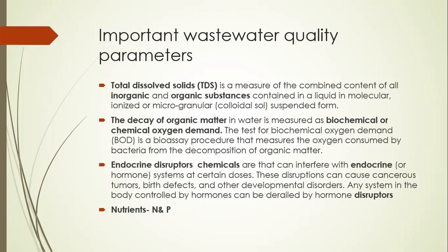How we can measure the presence of organic substances in wastewater is through the biochemical oxygen demand parameter, or BOD, and it measures the strength of any wastewater. So if you want to know your wastewater strength, the typical parameter that you would measure is biochemical oxygen demand, or BOD.